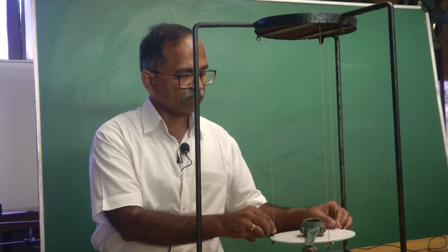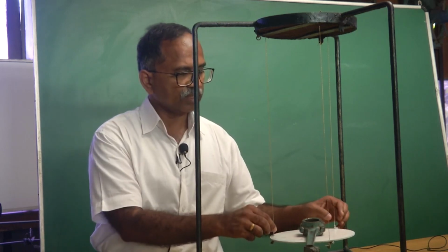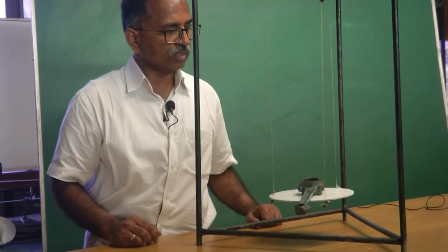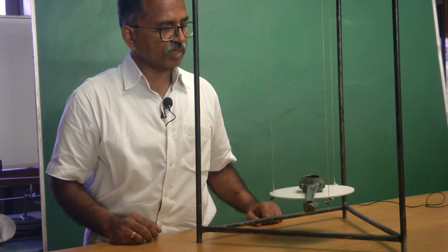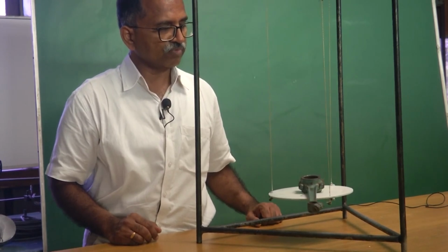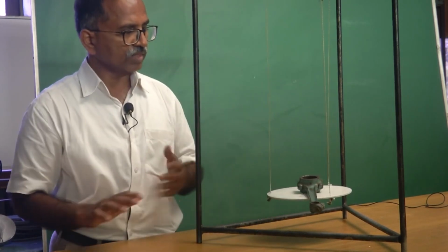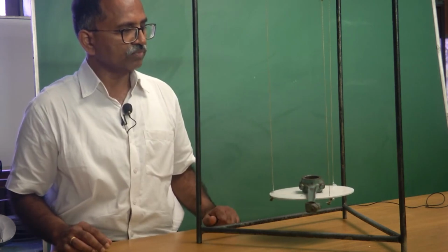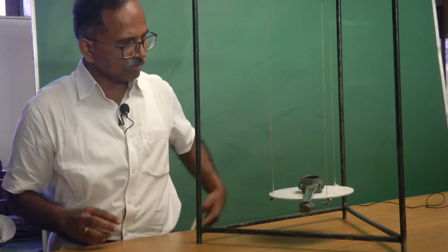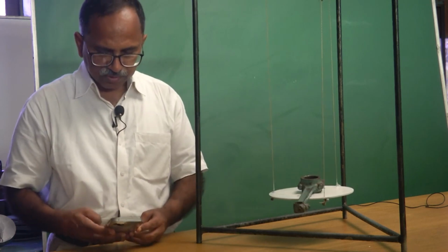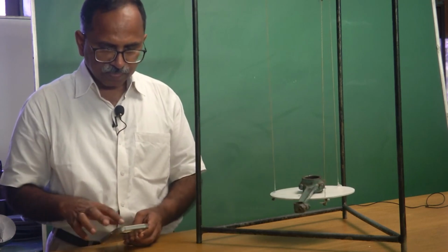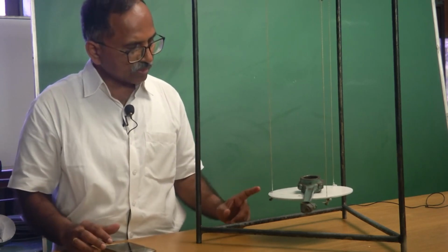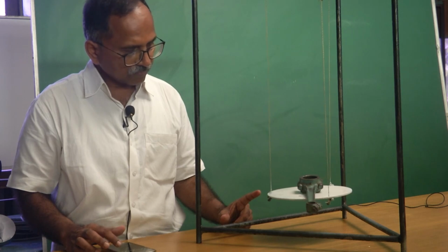And so, to get that period of oscillation, now I will give a gentle initial perturbation or small initial amplitude, and through that, as you can notice, the plate is swinging back and forth, and now we can record the number of oscillations and the period taken for those oscillations. One of the simpler ways is to simply record the period it takes to complete a certain number of oscillations, and we can now start the data.